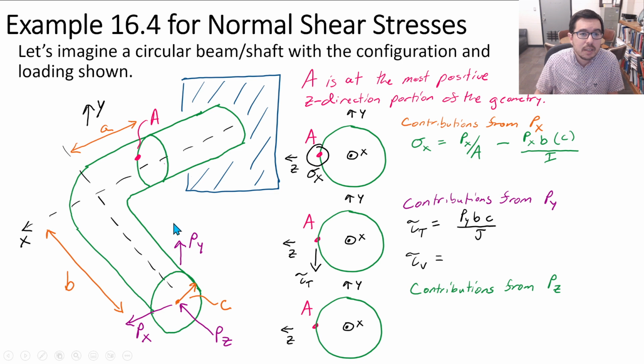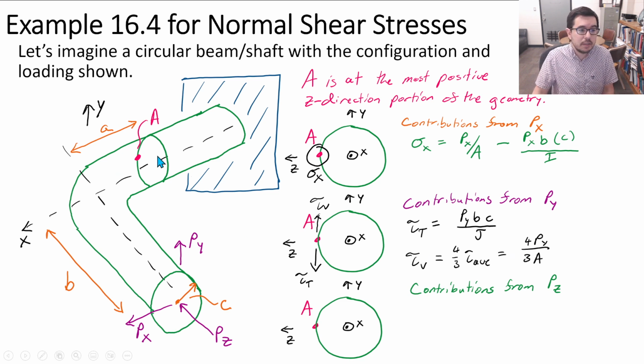So what are we going to write here? Well, we can first say there's going to be a shear stress in the positive direction, its average shear stress, and then we write 4/3 tau av, and that makes this calculation pretty fast, because it's a max, since we're at the neutral axis.